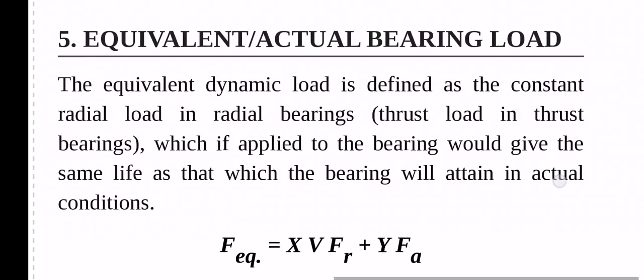Equivalent or actual bearing load. The equivalent dynamic load is defined as the constant radial load in radial bearings, or thrust load in thrust bearings, which if applied to the bearing would give the same life as that which the bearing will attain in actual conditions.